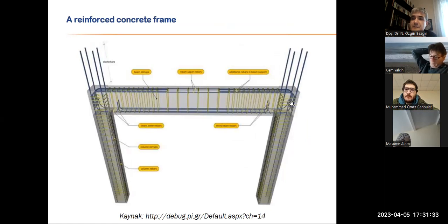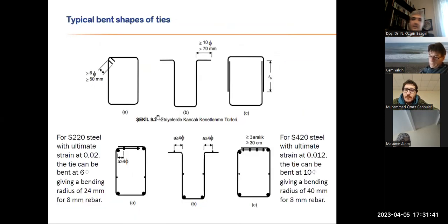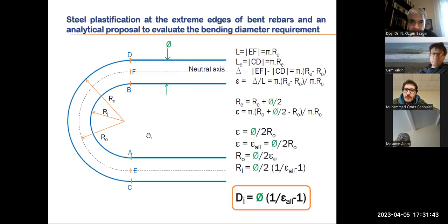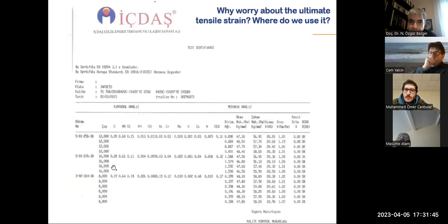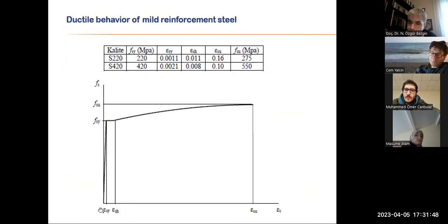When we purchase our reinforcement, we need to be extremely cautious about this plastic capability, because metallurgically, for steel producers, providing this part isn't a problem. Providing this part, it yields at 220. Oh my God, good for you. That's not a problem at all. Providing this part is the problem, because this ductility is only achieved by purity. And achieving purity is cost.